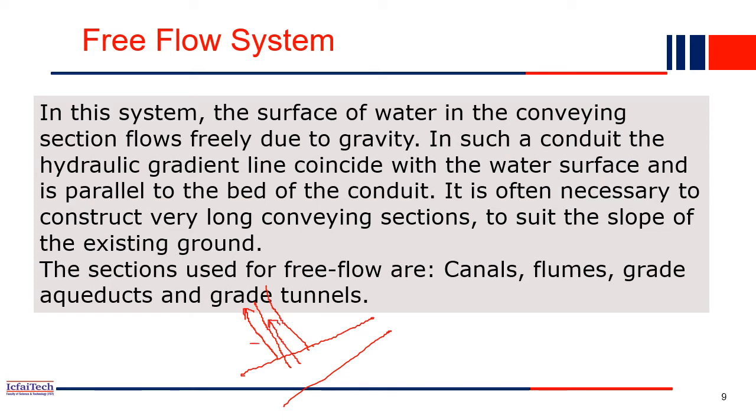So in an open flow system, we do not use any pump, right? Because where will you attach a pump? It is an open free flow system. So water should go by gravity force itself. So we have to make the slope such that water automatically flows and reaches the water treatment plant. So here we do not use any pump. As the water should go by gravity itself, sometimes we need to have a very long route also, because we have to use the ground slope, right? In that case, water may not reach the water treatment plant directly in a straight line.